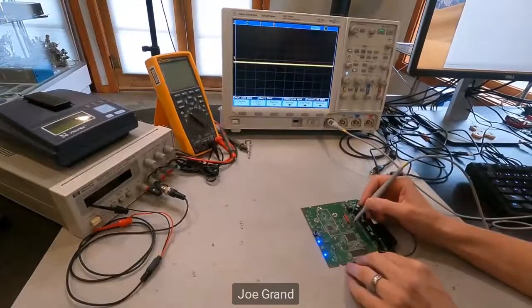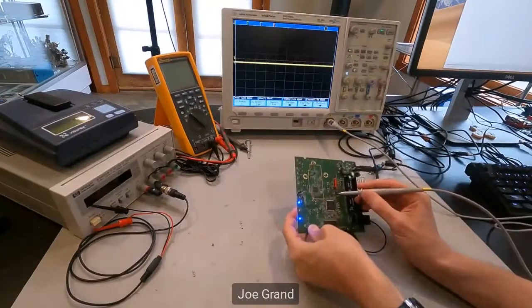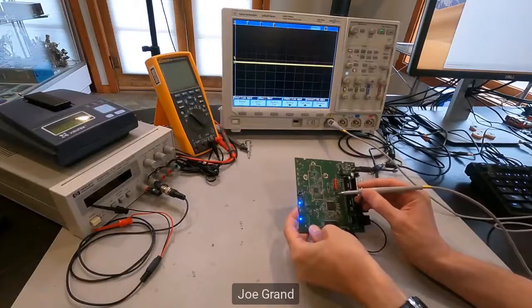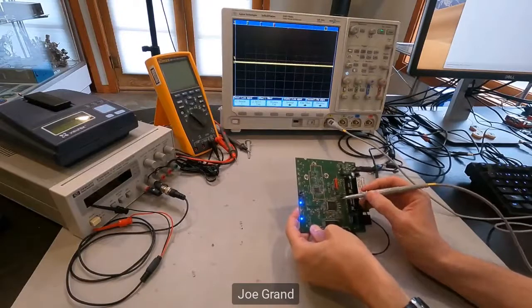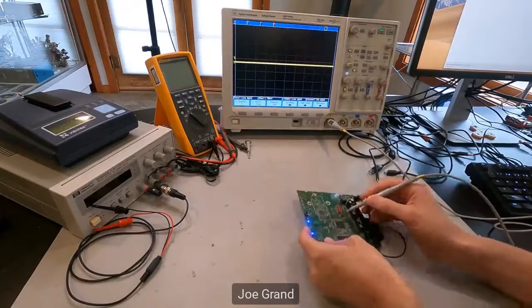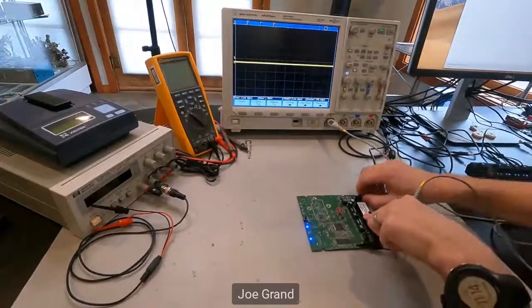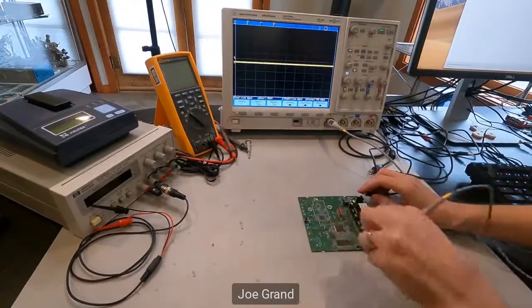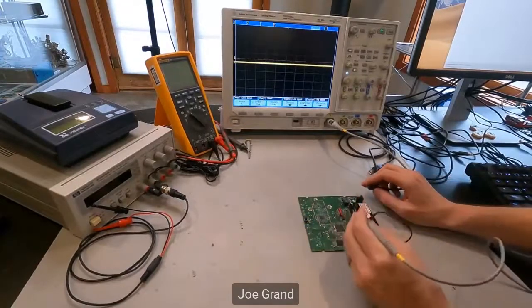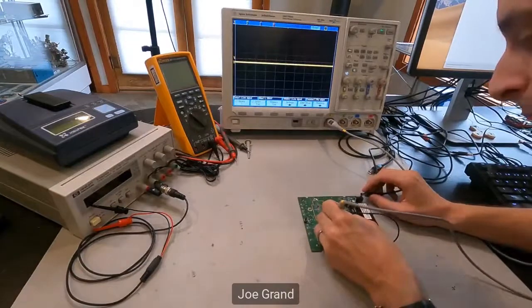This device here is a type of serial flash device. I'll talk about that more later, but that's really common for systems that don't have their own internal memory. So the firmware is going to be stored on a device like this. I bet you that if we look at that signal coming from that memory device to that system on a chip on power up, we're going to see activity, because generally the code gets loaded into the system on power up. So I'm just going to pick one.